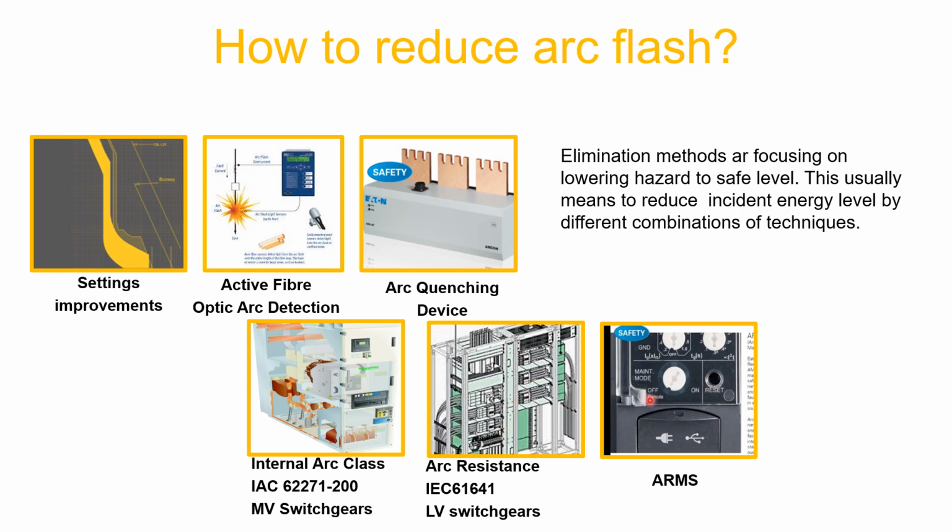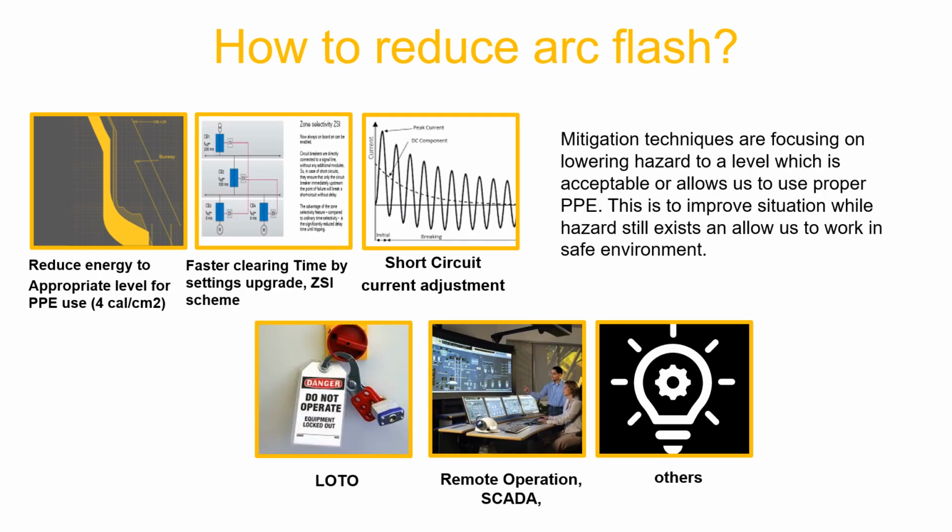You can also have special trip units in the low voltage breakers. You just have to ask the manufacturer that you would like to have it, whether it's Eaton, Siemens, Schneider, whoever, they should have it, and you have a special maintenance mode. This is called the arc flash reduction maintenance switch. It's a special function in the trip unit which you activate manually and which reduces the settings so the breaker works as fast as possible, at the cost of selectivity temporarily. It will usually improve the situation, but you have to check it first.